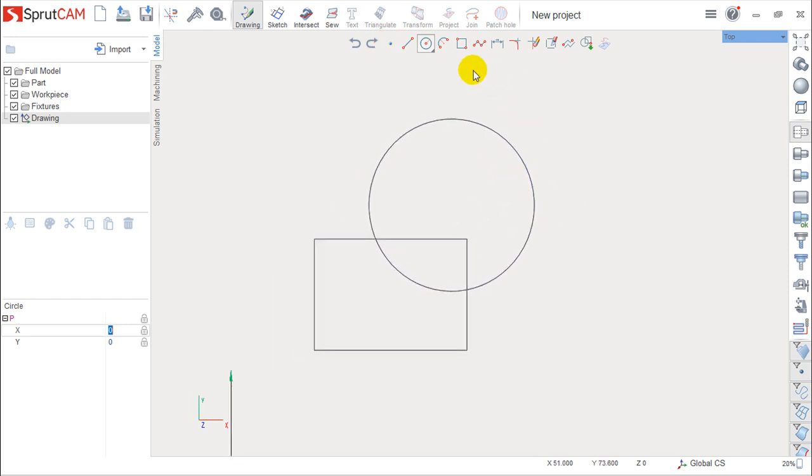Now, with this geometry created, I have also access to the functions undo and redo. Undo goes back, redo goes forward, which are also basic functions of almost every CAD system. And I have also the possibility to do trims, which recognize the geometry that is intersecting and basically trims those portions of the entities. I can also create chamfers or a fillet.